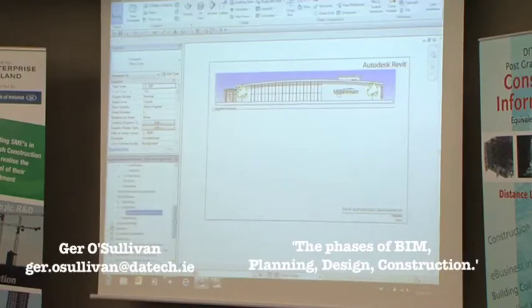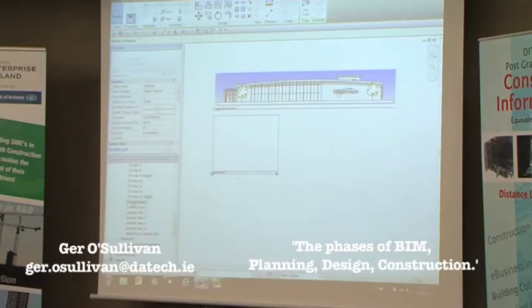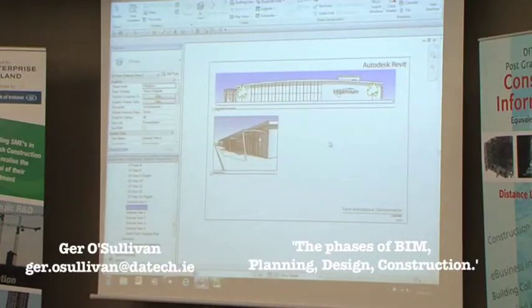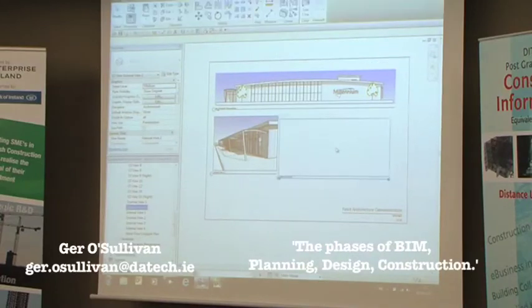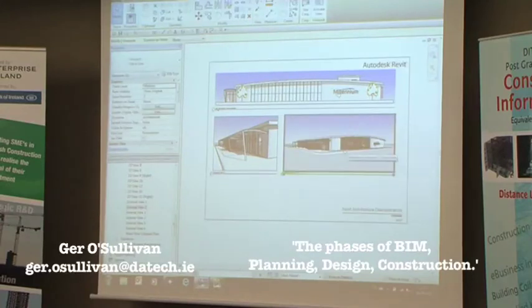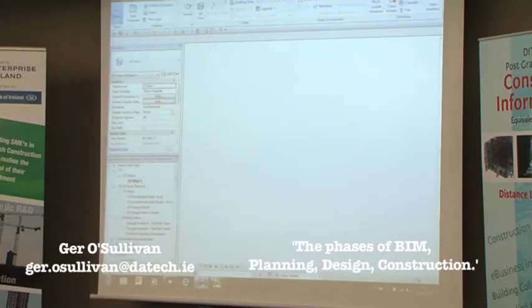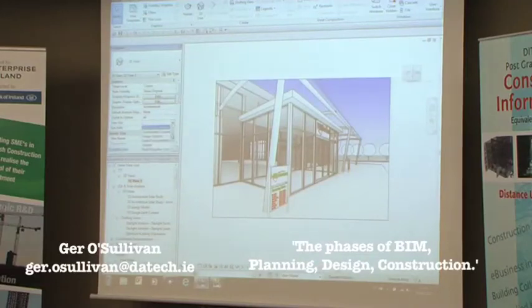Let's bring in some of the internal or external perspectives that we'd already set up. We'll take external view 1 and pop that in there. We'll take external view 2, and this is looking at the elevation where I would have added the curtain wall. So I don't have to go back and add that curtain wall to a camera view. It's automatic, it's there already. And the view I created, which at the moment is just sitting up here, because I didn't apply a view use set up here, I just need to apply that to presentation, and then we'll pop that onto the sheet as well.